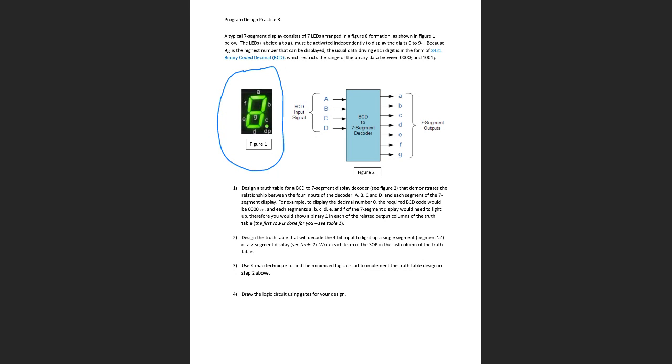The other kind of light source is a fluorescent light. Now, in a fluorescent light, they don't have filaments. There's basically an evacuated tube. It's not really evacuated, there's a gas. And when you excite the gas with a very high voltage, way more than the 110 volts you have it plugged into, it actually excites electrons in the gas, and they give off light.